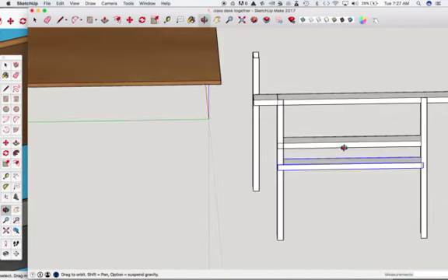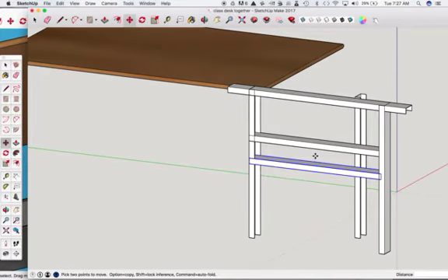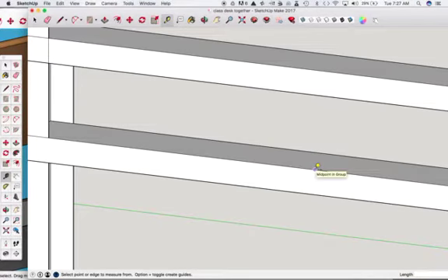So I have it selected now. I'm still on the Move tool. And so what I'm going to do is measure what I have and see how much different that is by 17. So, selecting the measurement tool, I just want to know the distance from here to there. And that says 8.97. I'm going to call that 9. So 17 minus 9 is 8. So I need to move this down in the blue direction, 8.